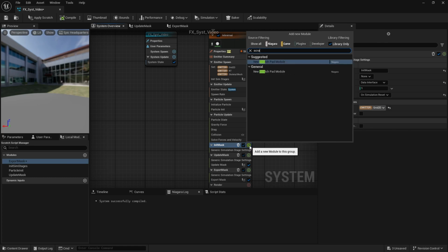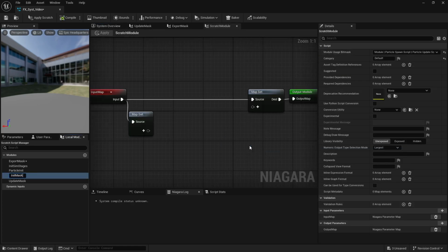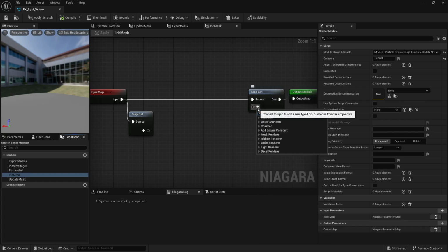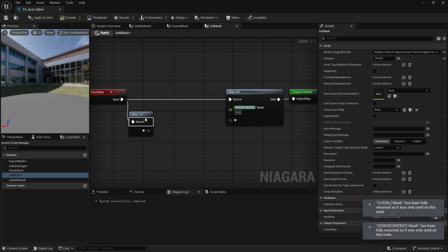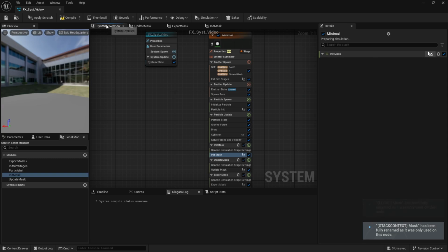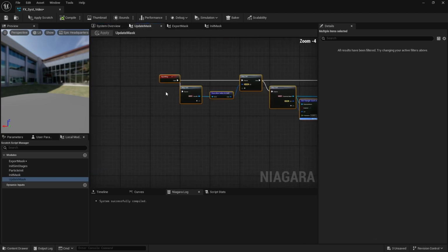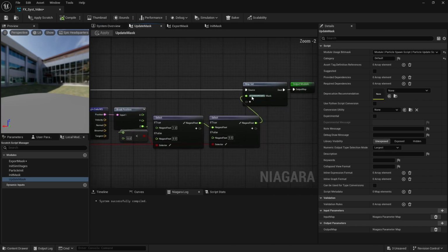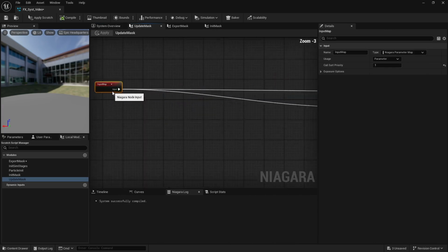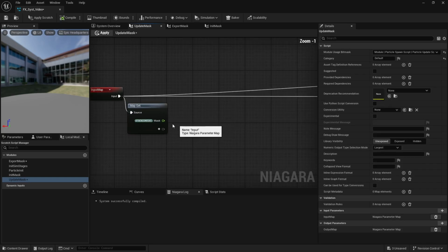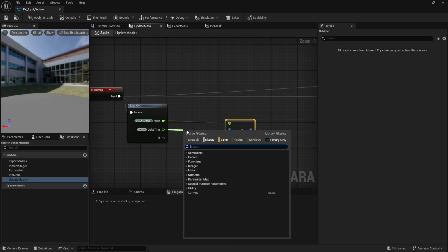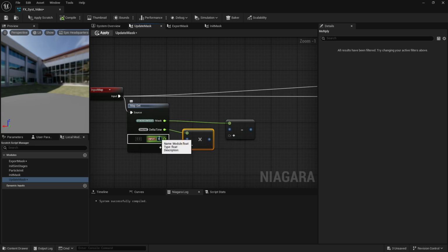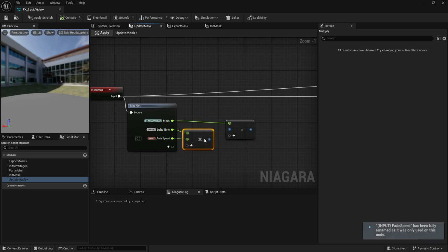I'm going to create a new scratchpad module to initialize this grid float to 0. Thus, once it's initialized, I can first access it in that other stage before setting it, and fade it out a little bit, meaning let's subtract the delta time multiplied by a fade speed control. And make sure it doesn't go negative.